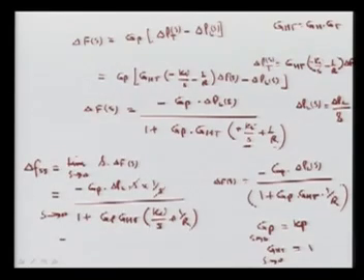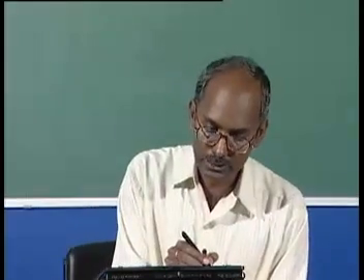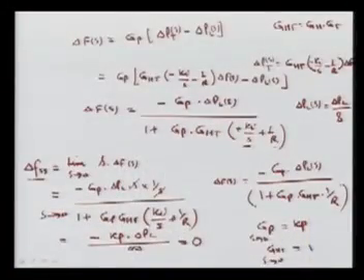So what we are getting here is minus Kp into change in PL divided by 1 plus infinite, which is again infinite, and this is nothing but 0. So this is our criterion that we have to get this value 0, means now the steady state error here is 0 and it is required. So we can see the integral controller gives error 0, and that is the requirement, and we also verified.